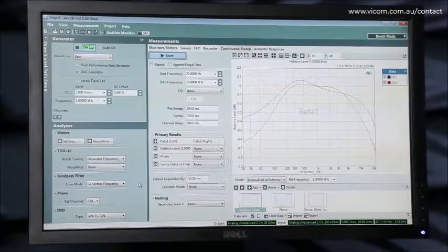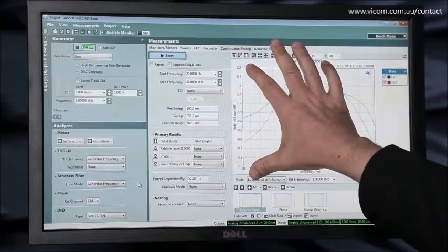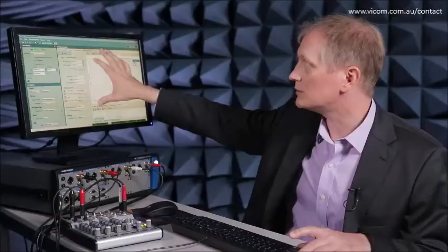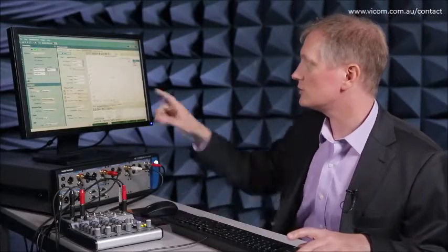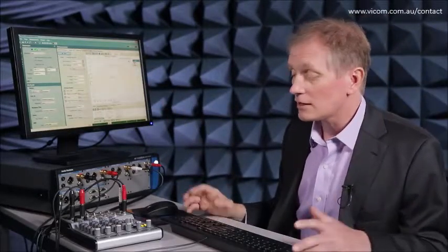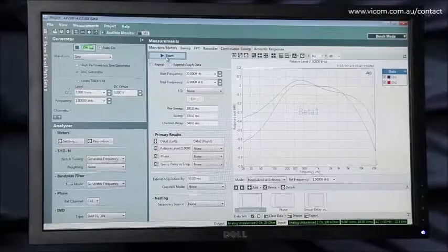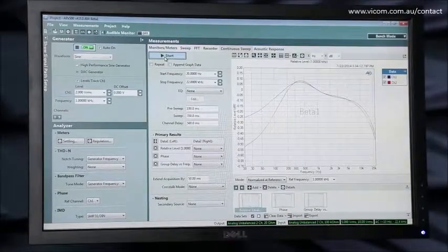Now we can get a closer view of what's going on with the frequency response, and you can see it's pretty flat. I mean, it looks like it's not, but remember the graph range here is quite small. It's only about a dB, minus a dB to plus a little bit. So we're looking over a pretty narrow range, and you can see there's some non-flatness there, and that's because this device has these continuously adjustable EQs, and I'm guessing that they're not perfectly flat even when the controls are right in the middle. That's pretty normal stuff there. There we go. But it's pretty flat.